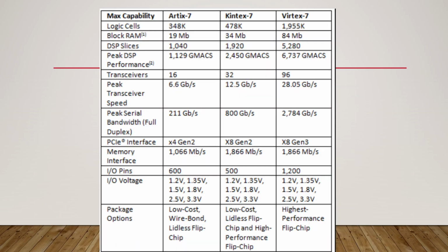We have discussed how we can reconfigure our Xilinx FPGA and what the programmable logic cell present in an FPGA is, that is the CLB. Everything we have seen. One example, the XC4000 CLB architecture, we have also seen, right? So next, you can see the comparison between Artix, Kintex and Virtex. Virtex is the high performance FPGA. It is the advanced version. It consumes low power, but Artix consumes the lowest power when compared to all others.